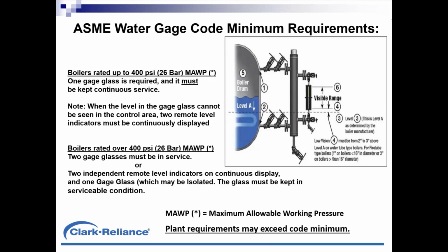And of course, your low water cutoff and alarms are going to fall within the range of the level instrument. So the whole thought here is once the water drops out of the level instrument, you've still got a bit of a safety bed below the bottom of the glass before there's any risk to the drum internals.